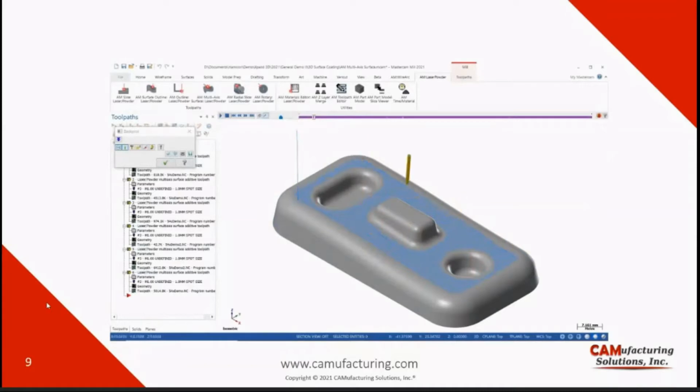The other strategy is using a chain and offsetting it on the surface. So for this fillet, we actually use the boundary chain, and it makes your toolpaths by offsetting the chain all over your surface. So this is very good for fillet surfaces as well. After that, we are going to see the 2 other holes on the boss.